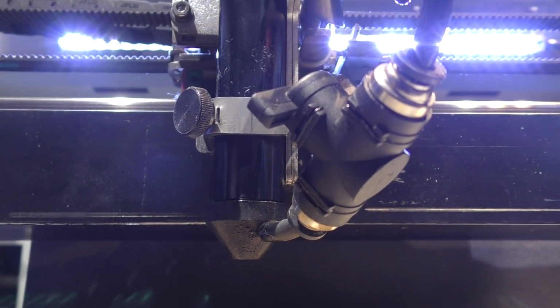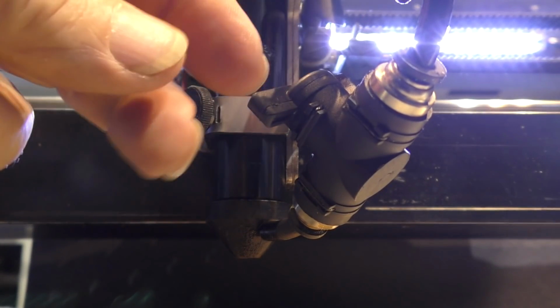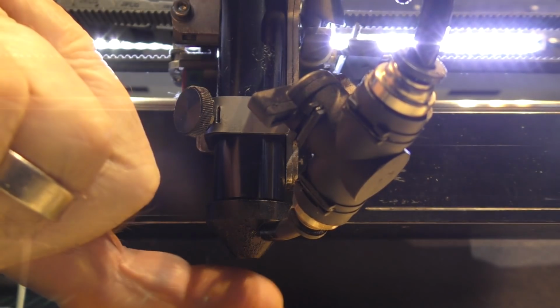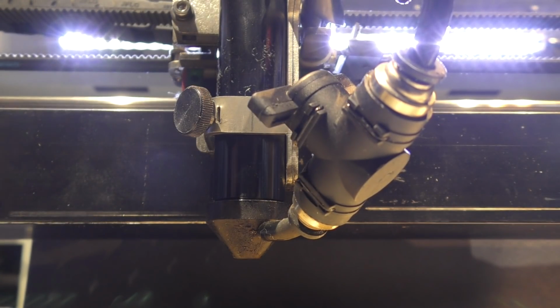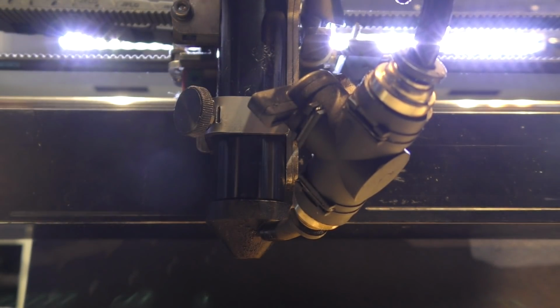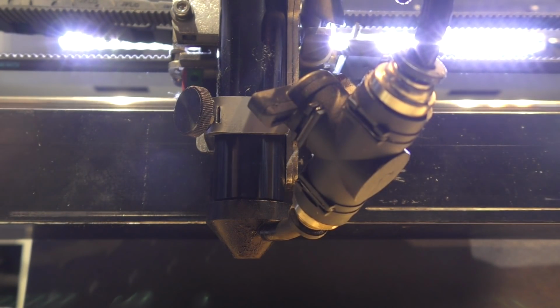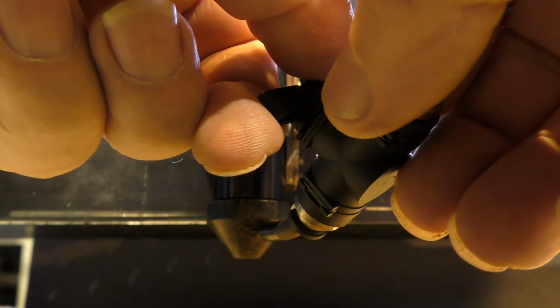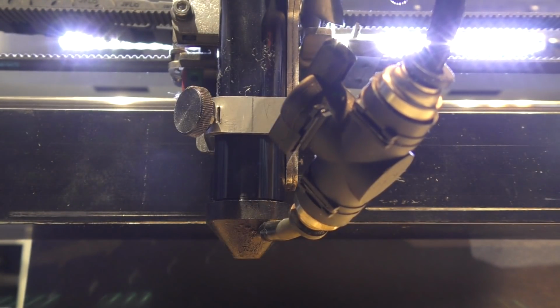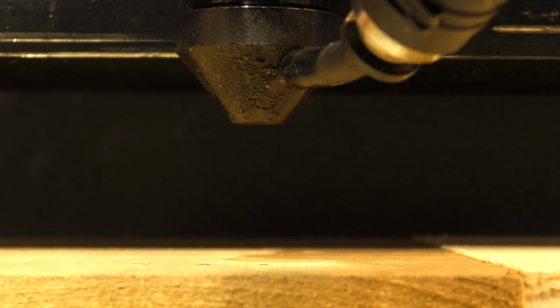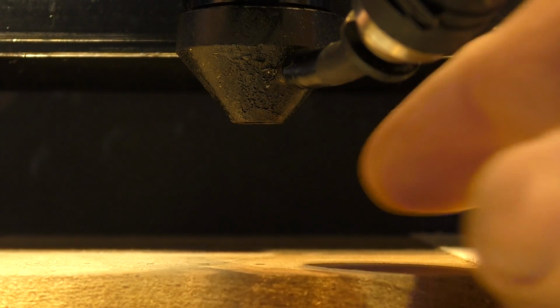Right, now just above my nozzle here, I've got a little tap. It's a ball valve, which is controlling my air assist airflow out of this nozzle. Now this nozzle has got a big hole in it, so there's not a great deal of directed airflow. It is a strange airflow coming out of here. It'll be totally chaotic. And there we go, you can hear it. Now that is my pulsing, silly little Chinese air pump that they supplied with the machine 6 years ago. We'll do the same test again with a 500 millisecond pulse.